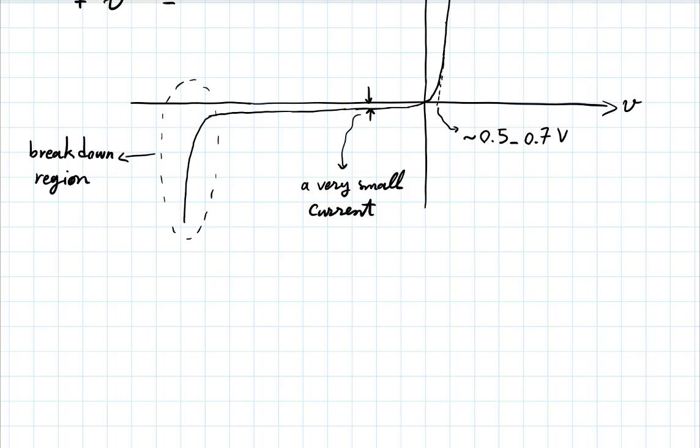Now, the physics of this breakdown, there are different mechanisms. Has anyone heard of a Zener diode? Zener diodes, which we will talk about again, have the Zener breakdown mechanism, but there is more than just that, even in Zener diodes. For instance, avalanche breakdown is another important mechanism. But anyway, the breakdown implies that it loses that basic diode property, where you were expecting almost no current in the reverse region.